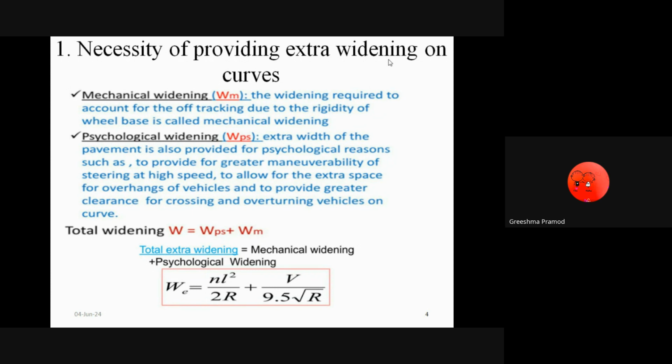Apart from that, the driver has a tendency to follow the outer edge of the road without taking the center path. So for that also, we are providing this extra widening.